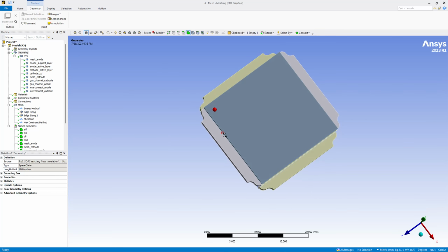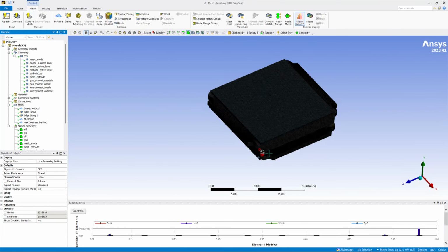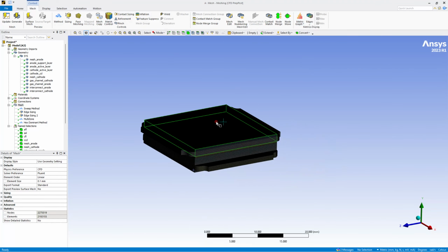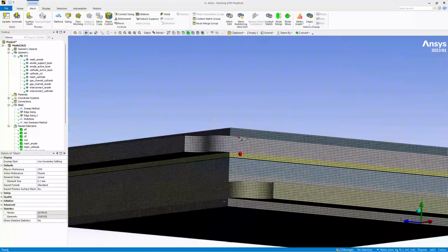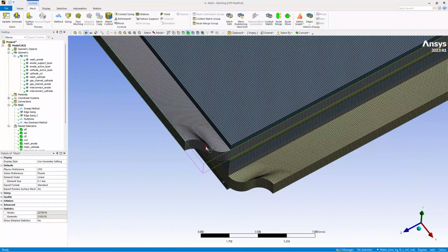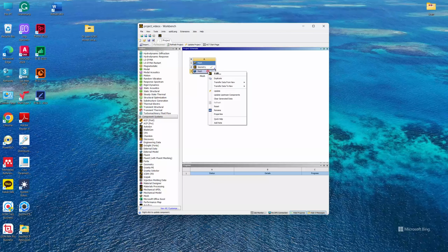Now as far as this session, we have obtained a very good mesh. You can close the matrix, and with around 2.2 million elements, this is a very good quality mesh with a few issues at the gas channels, but that can create some solver problems when we move to the Fluent problem. We will discuss that later in the next session. So for this, the mesh is completed and we can move towards the Fluent part.